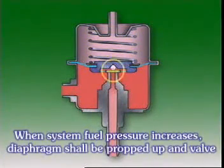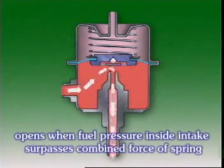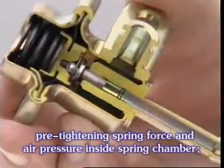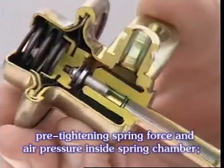When system fuel pressure increases, the diaphragm shall be propped up and the valve opens when the fuel pressure inside the intake surpasses the combined force of the spring pre-tightened force and the air pressure inside the spring chamber.